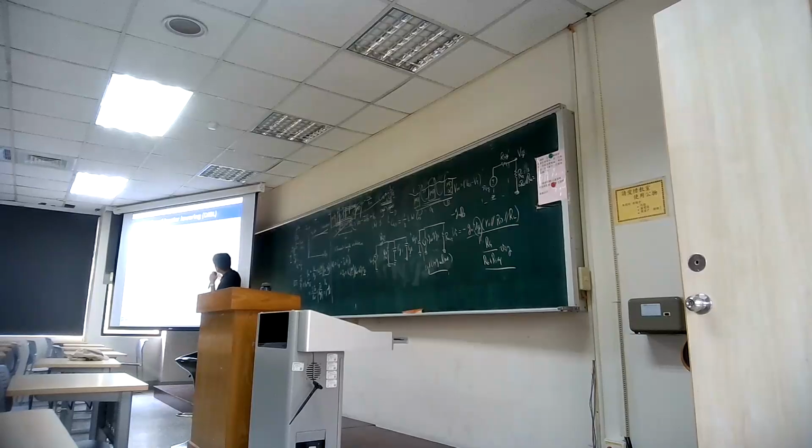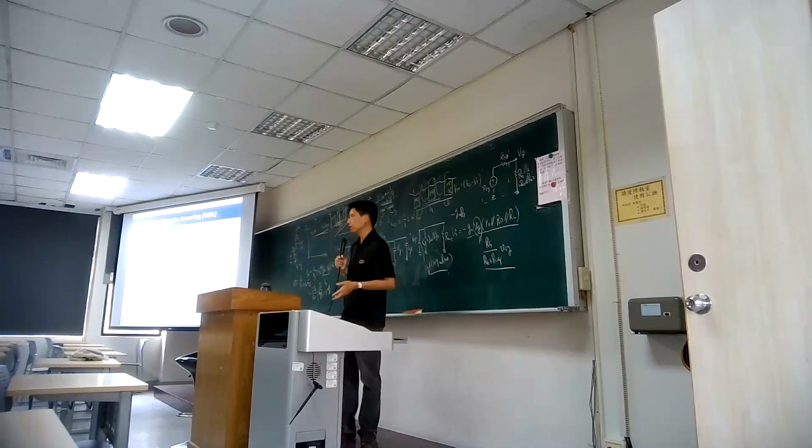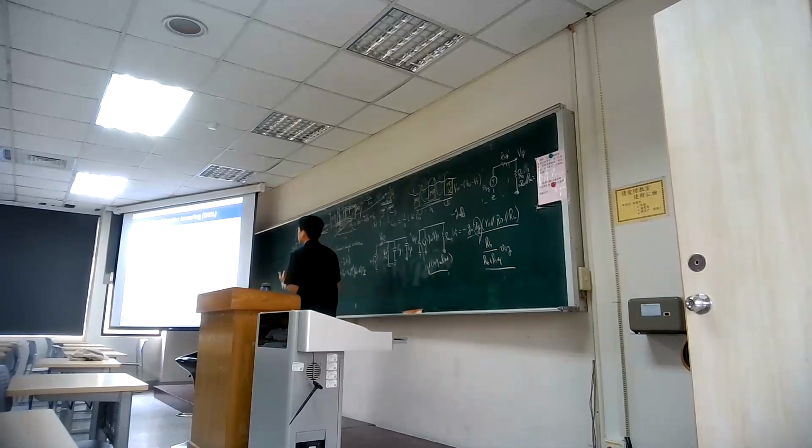So instead of still having a high barrier, like the one without drain voltage, we get a certain drain-induced barrier lowering because of the short channel. Okay, so we get the possibility that there is no barrier. So you need to consider, if your channel shrinks further, how do we control the current?